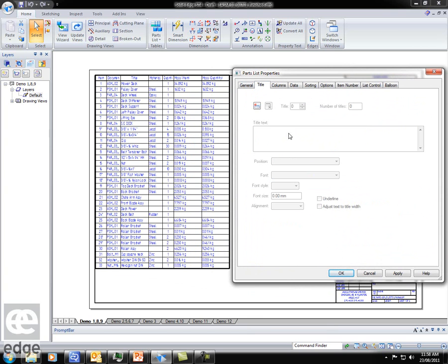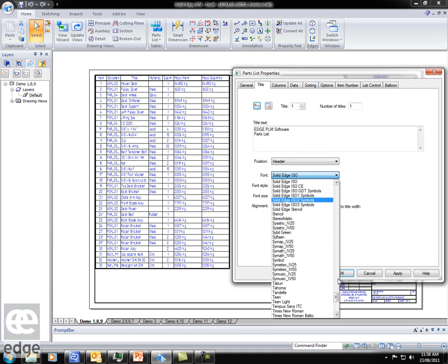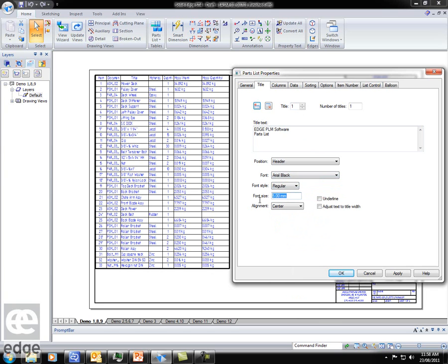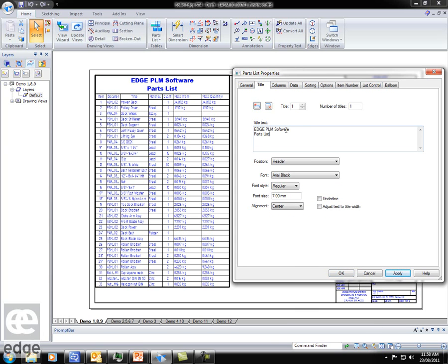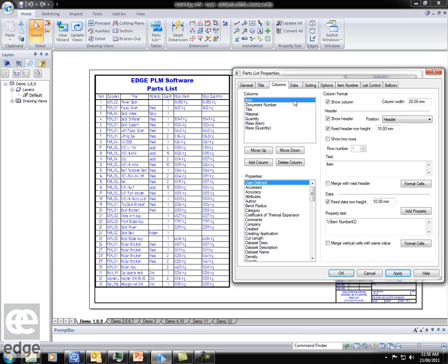First thing we're going to look at is just putting in a title. So turn on title. We can have multi-line titles. And another line. I have to be able to type. What font do I want? I can change the font. Let's go to something more spectacular. Arial Black. Size, make it 7. And now when we apply, notice that we see the update there straight away, and we stay in the property table. This to me is a huge productivity gain, because you can work here without going in and out all the time.